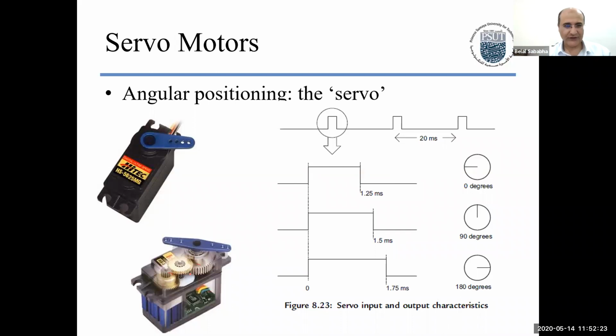I have a smaller one. No problem. These kinds of motors have a feedback mechanism. They have a board inside, a microcontroller inside to tell it how to behave. It has 3 lines. So if you see it on my camera, it has 3 lines: power, ground, and it gives you a PWM signal here. You give it a command.